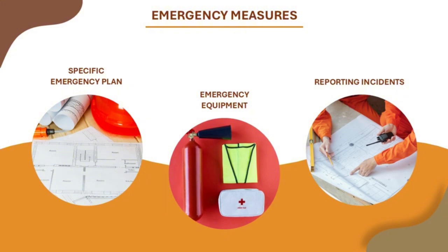Prepare a plan to deal with any critical situations, such as short circuits or electrical arcs, leaks of pressurized gas or liquids, accidents or injuries during operations. Emergency equipment. Equip the construction site with fire extinguishers, first aid devices and tools for containing gas and liquid leaks. Reporting incidents. Any anomalous event must be immediately reported to the safety coordinator and the works manager.